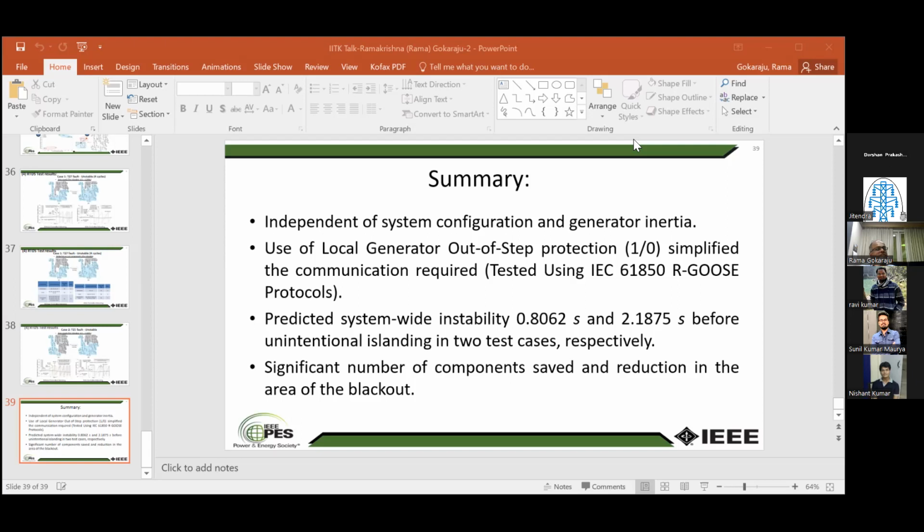It was around 2015 that the Hitachi engineers told us they did not have a single event misoperation. So they are having the RTDS simulations going in real time for those operating scenarios, and they are doing the power transfer based on those instead of the static limits on the line. They are doing the dynamic line limits.